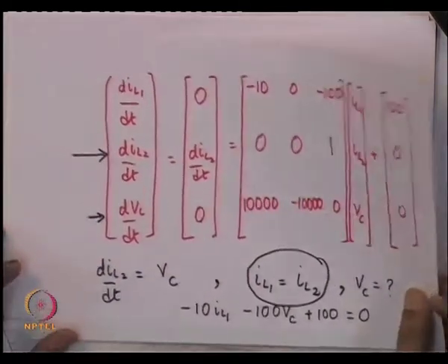Of course, now this seems to be a kind of chicken and egg story, because to know which elements or which states in your circuit are associated with slow or fast transients itself requires you to do an analysis of the system. So, you have to do a full blown analysis and then find out which states are associated with the fast transients, and then you can make this modeling simplification. But actually engineers do not do that.